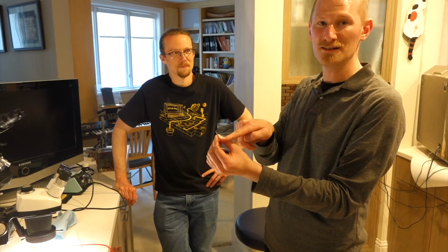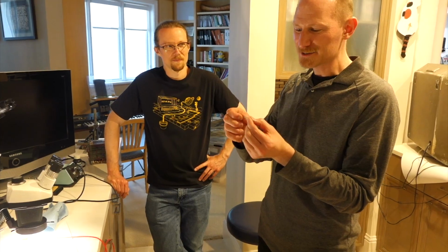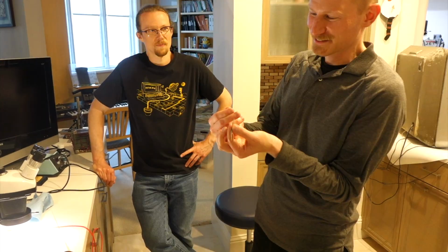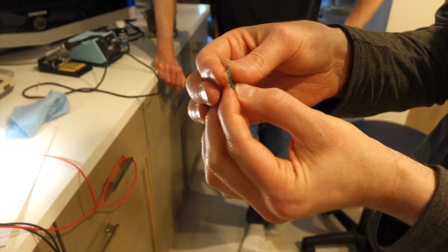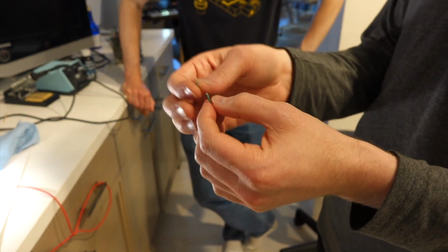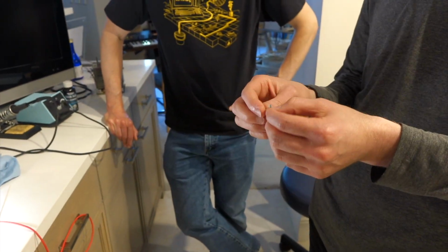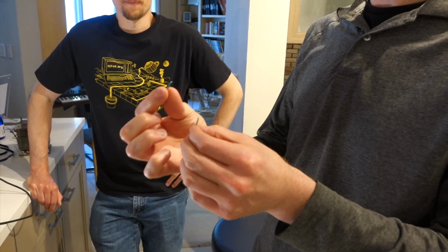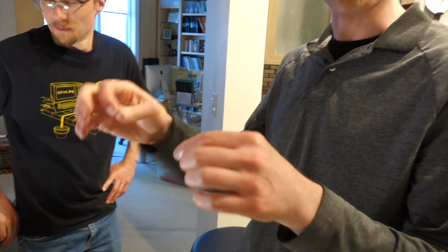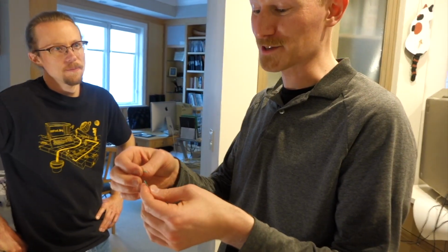That's right. But yeah, actually you can get hoodwinked, because on Amazon, if you search for stuff like speaker cable or coax even, you'll find a cheap one, and then hopefully they'll say it's CCA. The failure mode is funny, like the crimp is actually okay. The break is in the middle of the wire, which is unusual. I think it's the corrosion that really gets it, because when you pull the thing apart, there's nothing there, and it's because the aluminum has just turned to powder, and the copper layer on the outside is so thin that it basically just falls apart all by itself. The copper powder just floats off. But I think what makes it worse is the molding process. Whatever is in the PVC used to mold the wire makes it even worse, because I've seen a lot of these where there's a lot of powder in there.